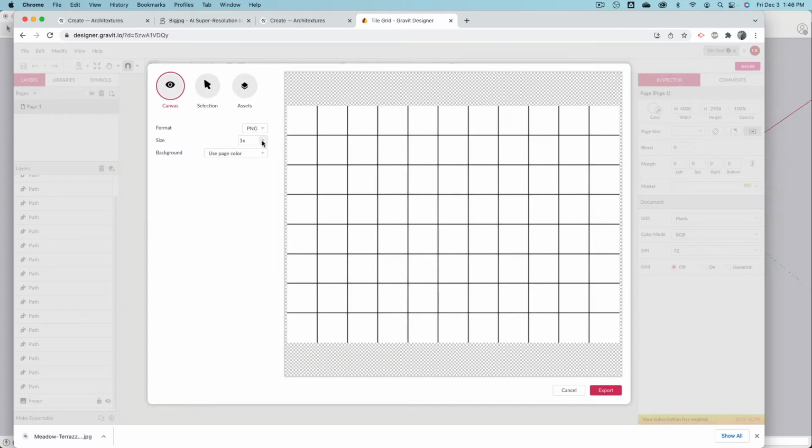Okay, so I do not have to change the size here. When I go, this is like a 2 times bigger image, so it's like 8000 by 6000. 4 by 3 is fine. This is all good. JPEG? Don't use JPEG, because then we get artifacts. Here we really want to have PNG. PNG does not add compression, which is also why PNG images are bigger. Export.